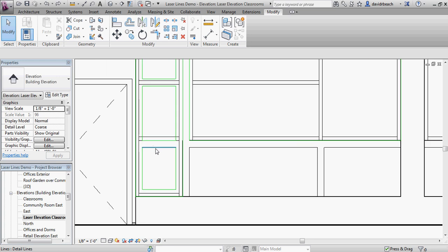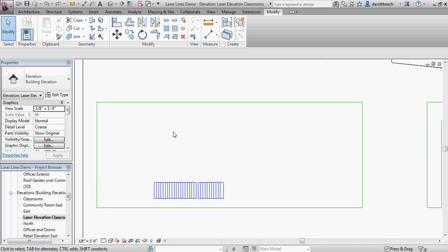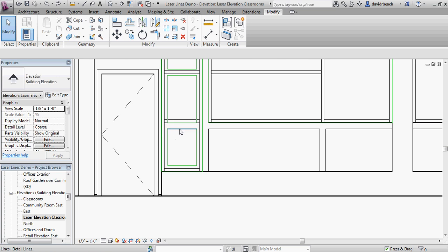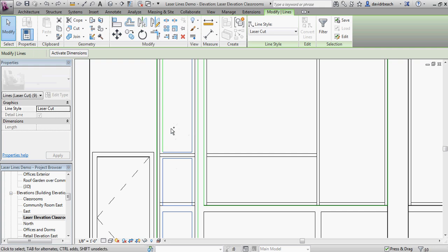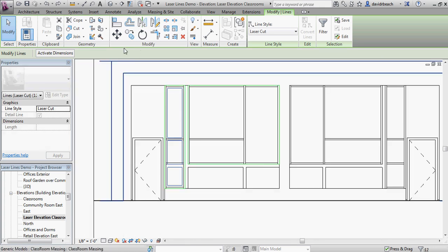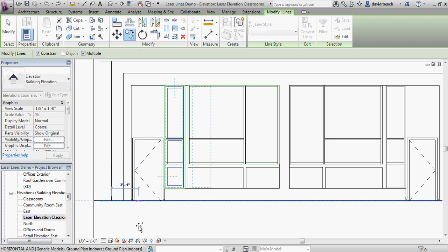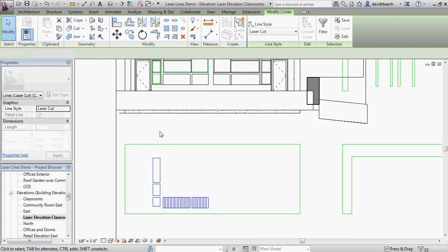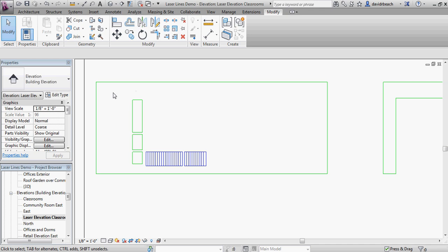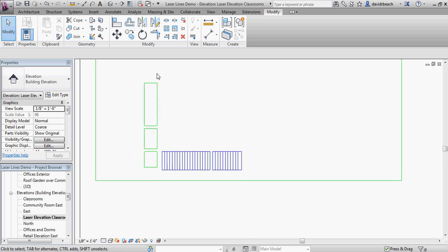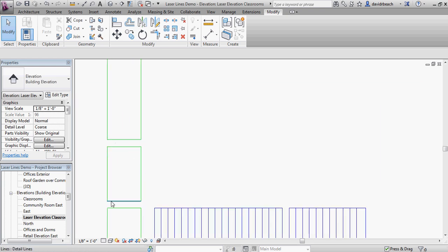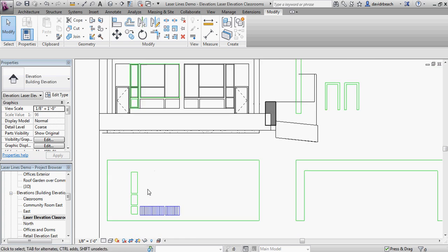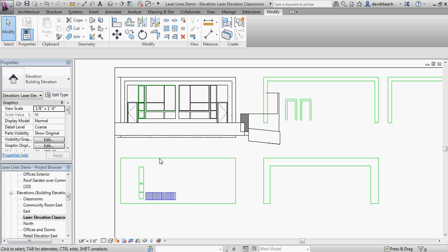The other thing I could do, let's say I actually want this back piece to be open where the window mullions are as well. I might want to come in and add in this last set of windows, copy, and I know that would give me a complete cut all the way through, and that would give me a location to begin stacking the mullion pieces up on this as well. So that's actually an opening, and you can begin to see where the mullions would be in location. And then I'm stacking pieces vertically up off of this back template.